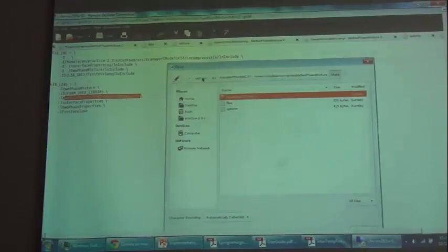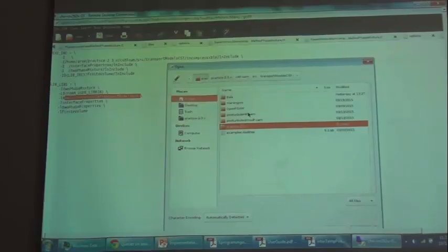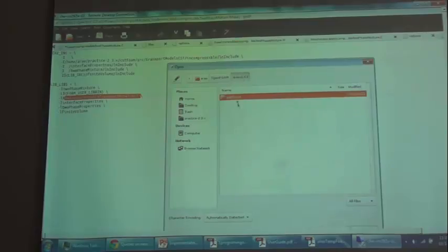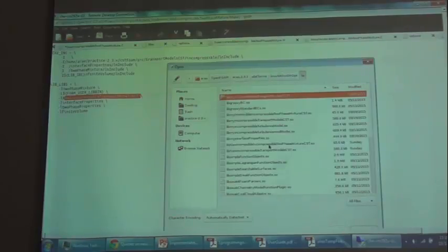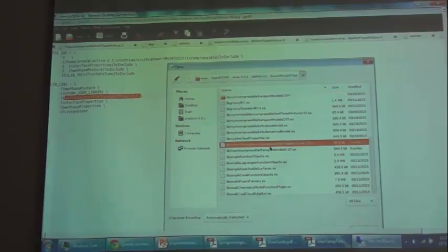If you want to see that again, so this is the .so file that gets generated once you compile these files. Now that these two files or classes, the modified classes, have already been executed, the next step will be to modify the original InterFOAM solver.